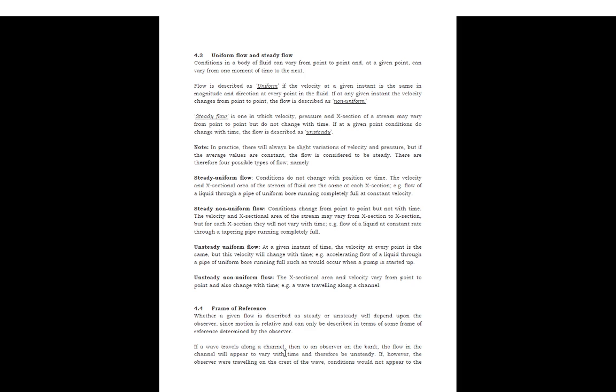It gives us the practice of classifying our flow as steady uniform flow, steady non-uniform flow, unsteady uniform flow, and unsteady non-uniform flow. For steady uniform flow, all the properties or parameters that determine flow remain the same from one point to another and also with time.